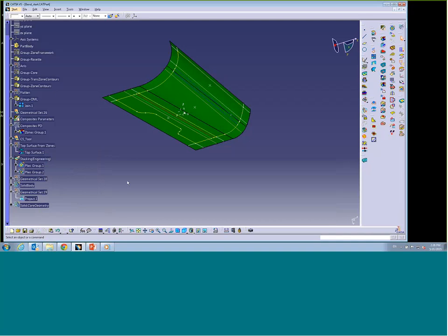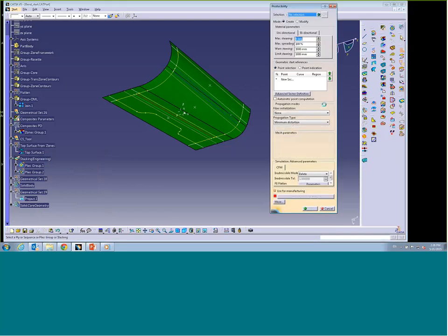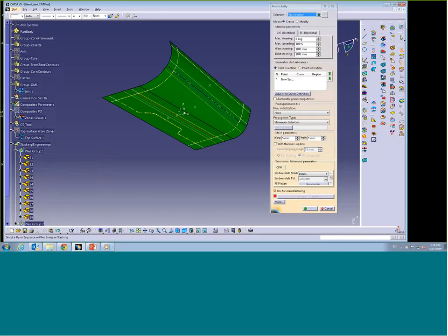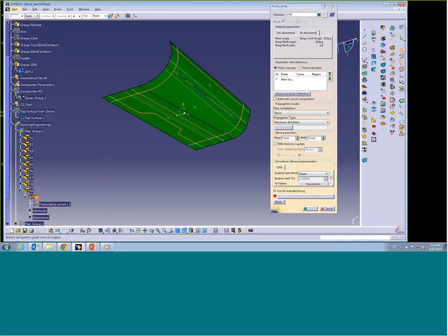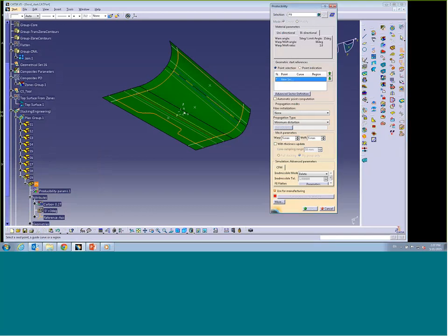With the producibility analysis, I can actually analyze how the plies are going to drape over the OML surface. So that's this tool, producibility analysis, and it tells me, okay, which ply you want to try. Let me try the last ply, P9. Let's see, by the way, it is at 0 degree carbon 0.27. Okay, and the starting point, imagine that you drape your ply over the OML surface. That's where the ply or fabric will first touch the OML surface. Let's say I want to start with the middle. So it shows me, by the way, warp and weft direction.